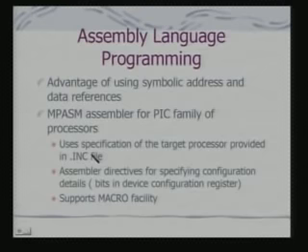In fact, if you are using an 8086 assembler or 8085 assembler, your processor configuration is pre-specified. It is part of the assembler itself. But here you are using the assembler for a variety of processors. So, you have to specify your target processor by selecting an appropriate .inc file. This is a very important exception here.